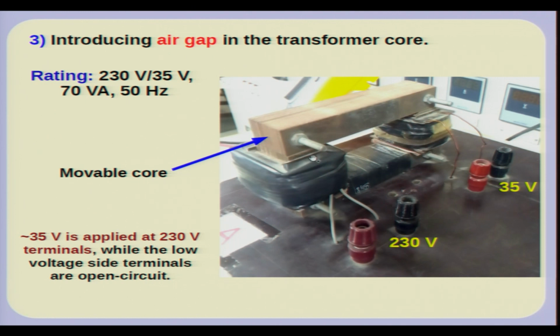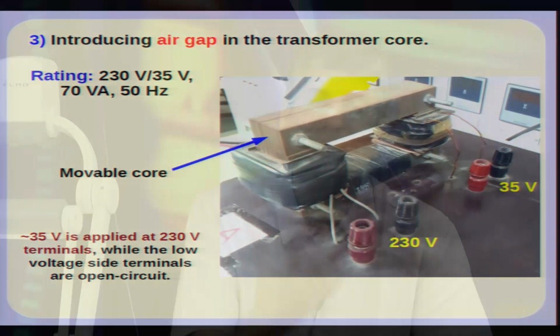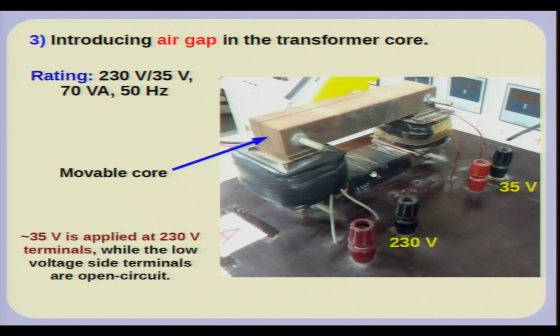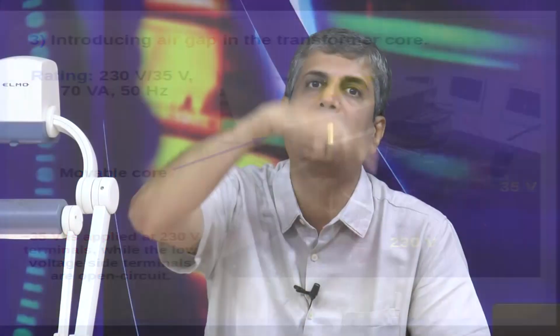transformer, is high because you have got a ferromagnetic core. I mentioned to you, because you have got more flux for the same amount of current, because of the high permeability, your L, the constant L, is quite high. This happens because you have got a ferromagnetic path, but in case you actually make it an air path, okay, partly you remove the I core, so now the flux will flow through the air. In that case, the self inductance of the primary winding reduces, that L11 reduces.